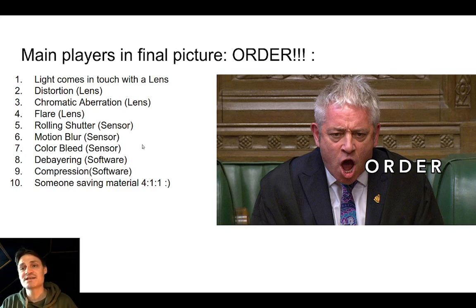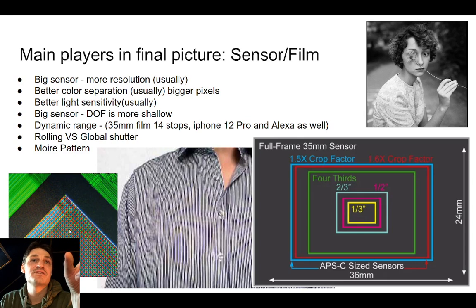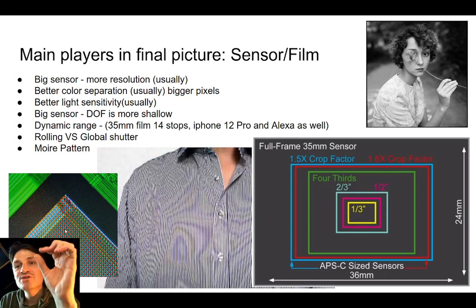So this is something that's happening inside of the camera or outside of the camera, because the material that the sensor will produce will be raw material, but we're not working with the raw, we're working with the EXR, for example. And raw will have not-debayered material, how it was recorded. We have one pixel with values red, green, blue, but on the sensor there are no single pixels with values red, green, blue. There are three pixels next to each other, red, green, blue. How they are connected together, that's called debayering.